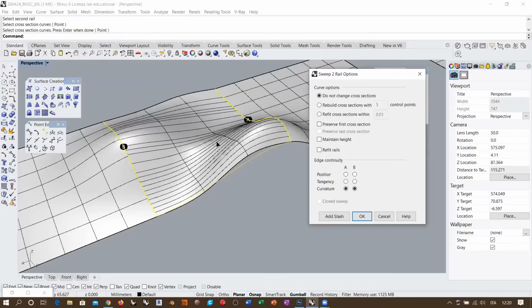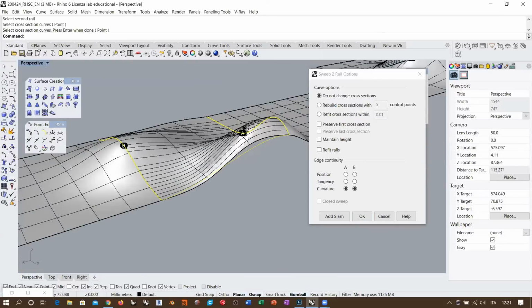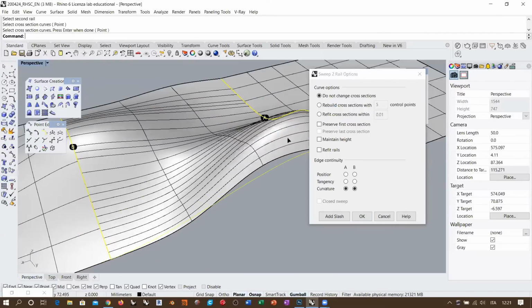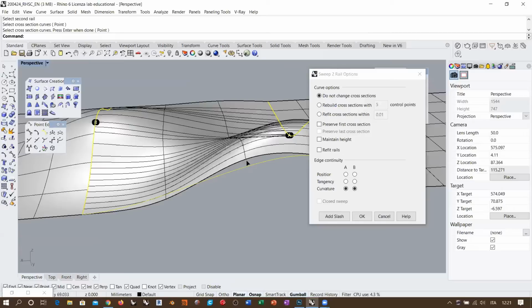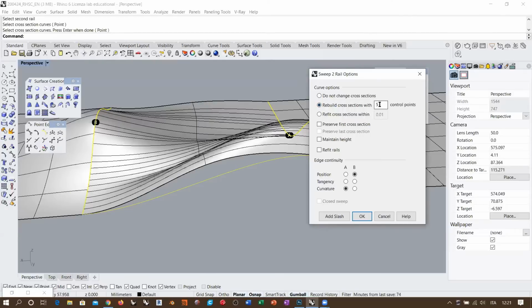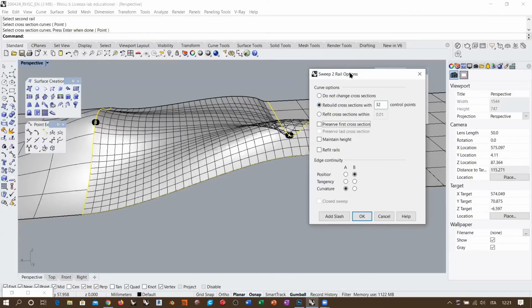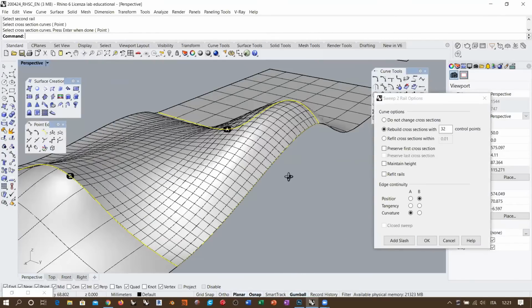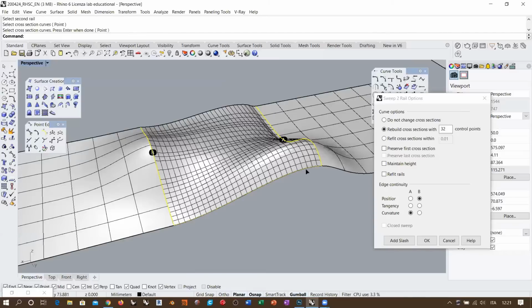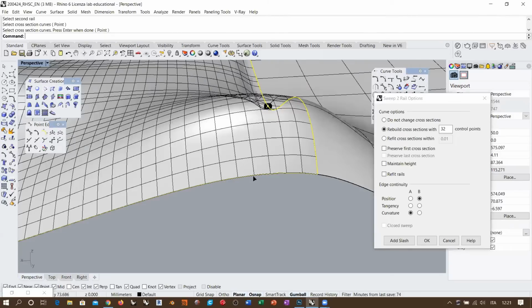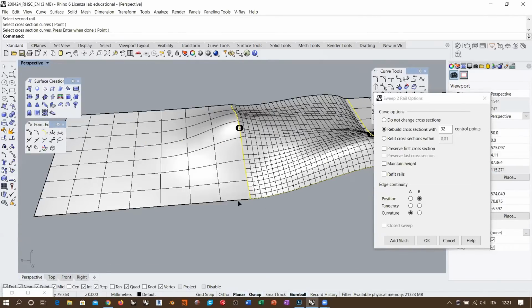The other thing that you can do eventually in this case is use the proper topology, like 6 control point degree 3, but at the same time rebuild the cross section with, I don't know, more control points. Now, if you do this, you are saying basically that your cross section has become more and more complex, okay? Yet this cross section, which in this case adheres to the original shape, is not curvature continuous with this surface, not even with this surface, okay?